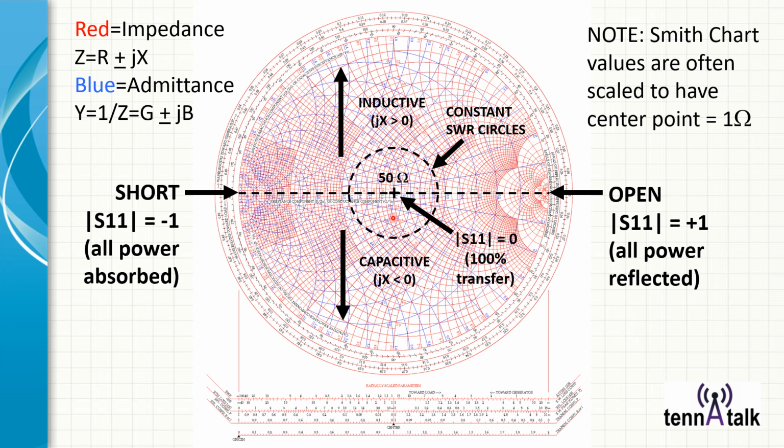Then you'd multiply back by what is called your characteristic impedance, which is 50 ohms in most cases, because that's what your rig is set to, and that's what most coax is used at, is 50 ohms. So that's a little bit about the Smith chart to begin with. So don't get too shook. Just take a look at this for a little bit, and it'll start to make sense in a moment.